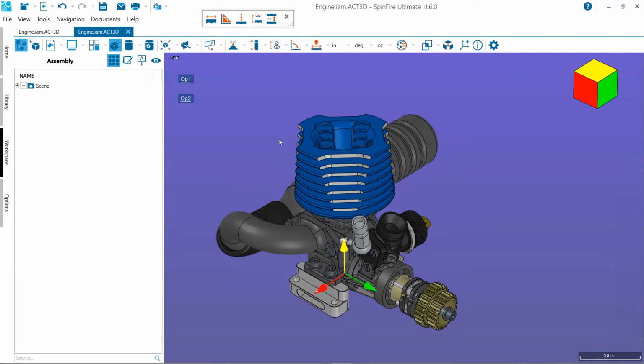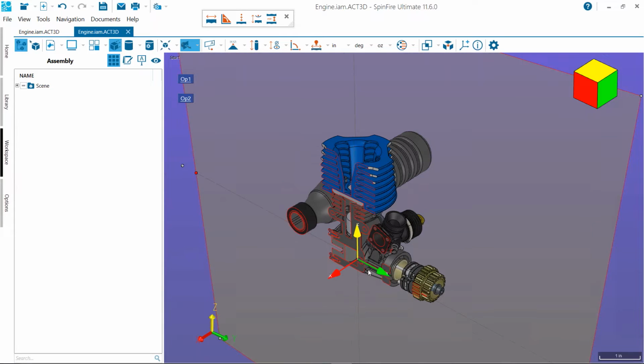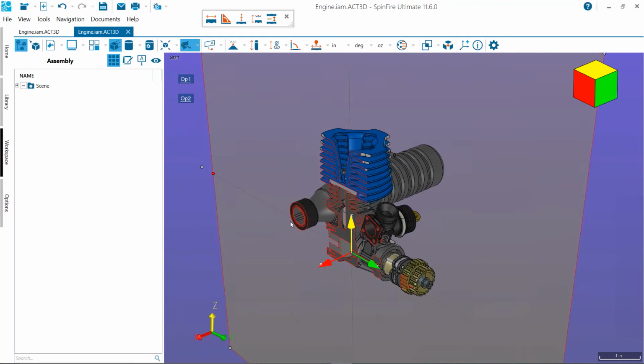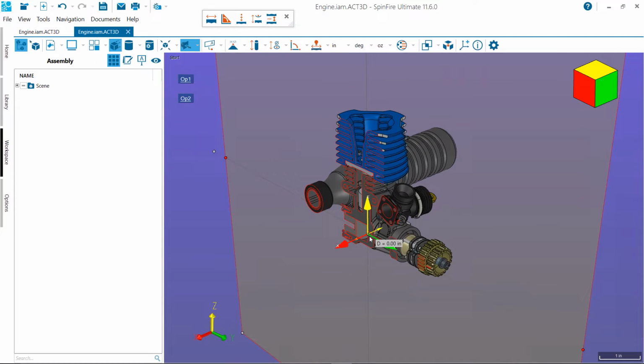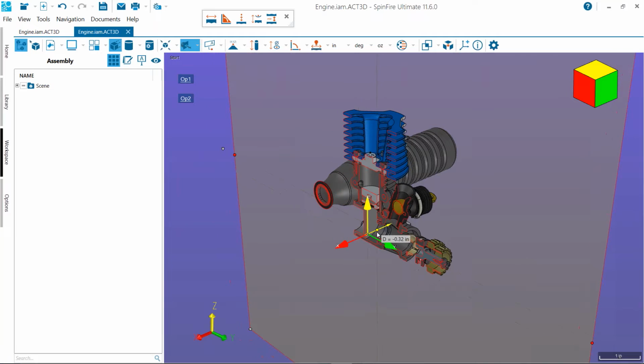Sectioning. A lot of people use section cuts. Pretty much everybody uses section cuts. In the past, it's been how many section cuts? One. That's all you could use. So if I turn my section plane on, it's going to be the default section plane through my default axis here. Right? And that's my YZ section. And it works the same as before. I can move that in and out.